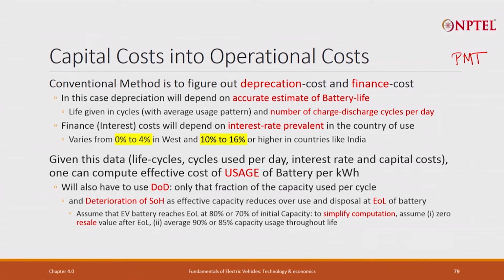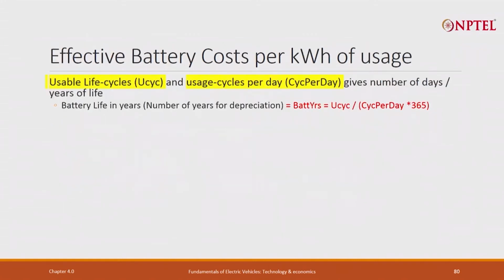You do not necessarily empty the battery every time before you charge it. When the battery is coming towards the end, you will like to charge it. So, on the average we will assume 85 to 90%. Sometimes you may discharge it till 95%, sometimes you will fill it up to 80%. So, that also we will take into account.